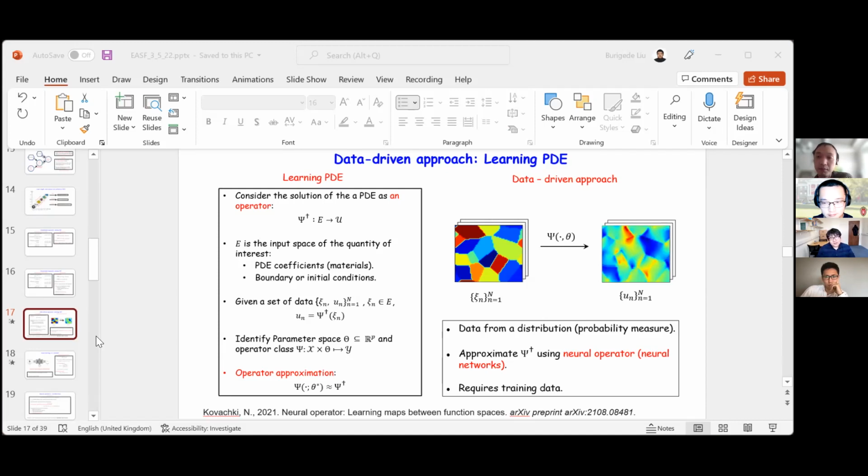No. So, you can basically compile a Python object into an executable file and call it using Fortran. But what we have done here is we explicitly coded the neural network in Fortran for the VUMAT. The reason is because it's faster, and Fortran is an old language. Really, why we're going through this hassle is because we're trying to use Abaqus, and Abaqus forces us to use Fortran. And machine learning is done using GPU in Python.